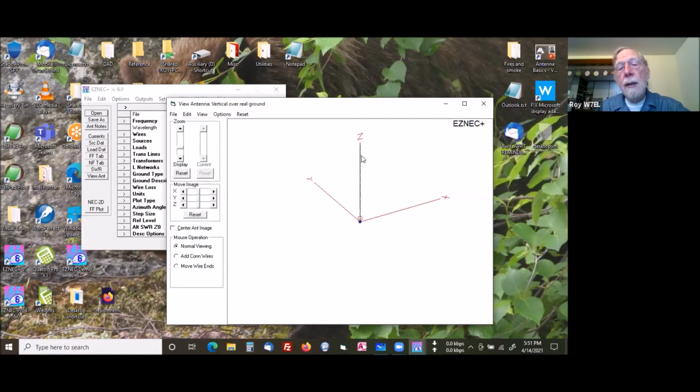And the nature of the reflected signal, first of all, this path is longer, so you'll get a phase shift because of that. But you also get both a phase shift and an amplitude change because the ground isn't perfect. Only if the ground is perfect will you have this complete reflection.